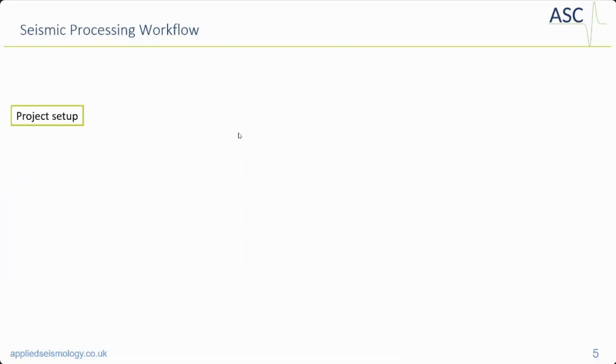So once we have set up our project, the next step is to get seismic data into InSite. The standard process would be harvesting this data from the continuous record. This tool is only available in the full version of InSite. So in this case, we have to import either raw, continuous data into InSite, or import pre-triggered events into InSite.